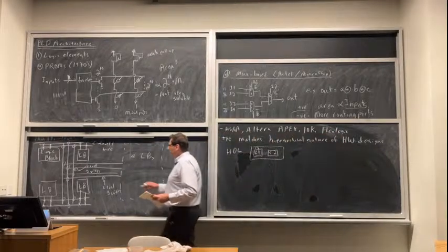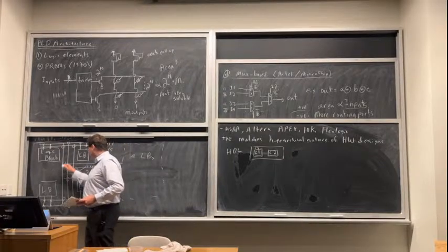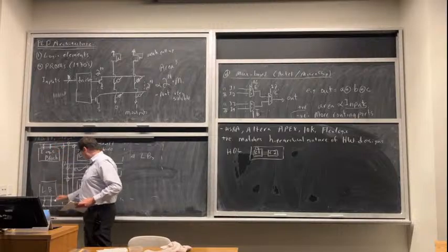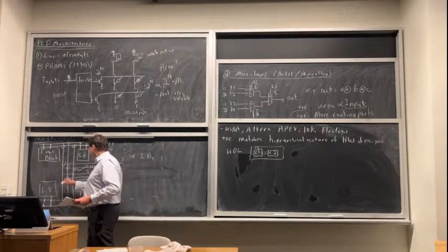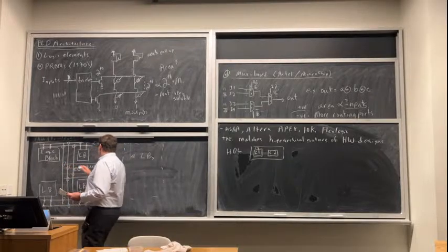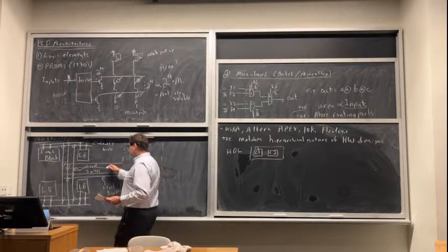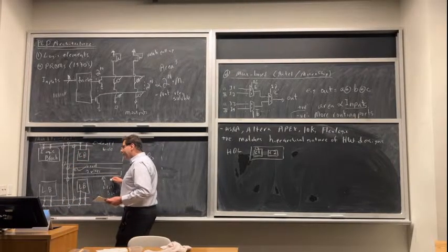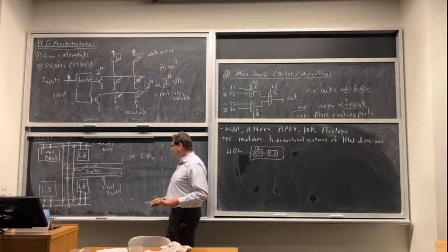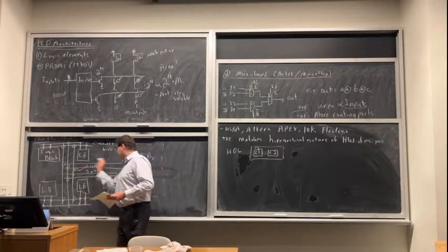So we're exploiting that in this architecture by not building as many wires as we go up. At this level of hierarchy, we have 2 wires here and 2 wires here, so 4 total wires. But when we go to the next level, we only have 3. And if I now compare the number at this level to the number of level 3 wires, I have 3 wires here, and I have 3 wires in my mirror image here at level 2, so that's 6, and then I only built 4 going between those big blocks.